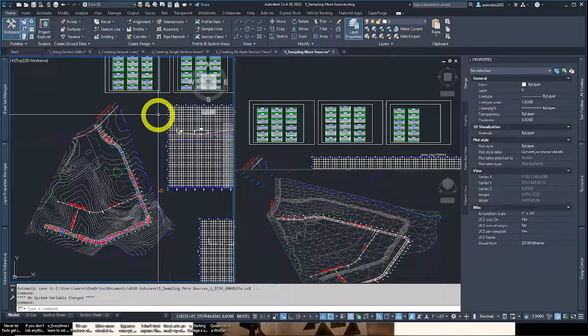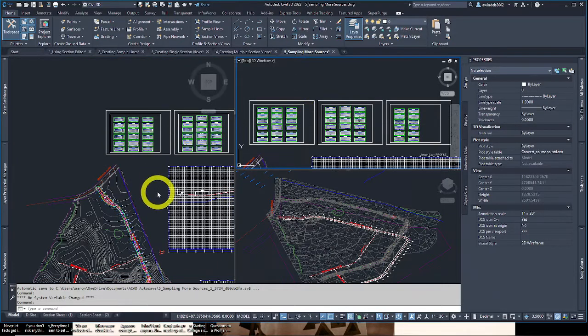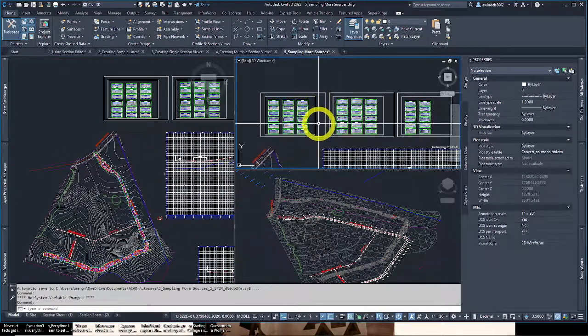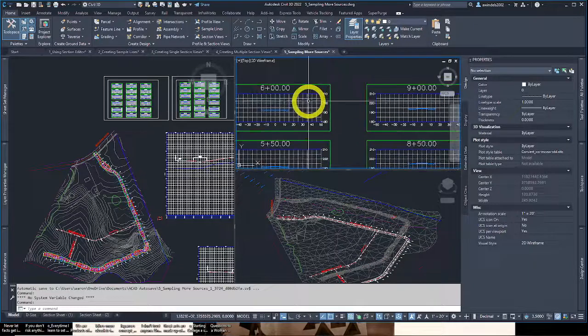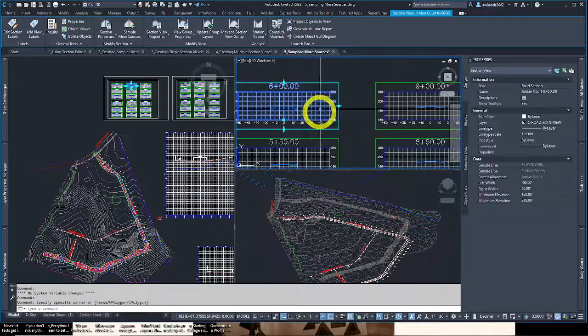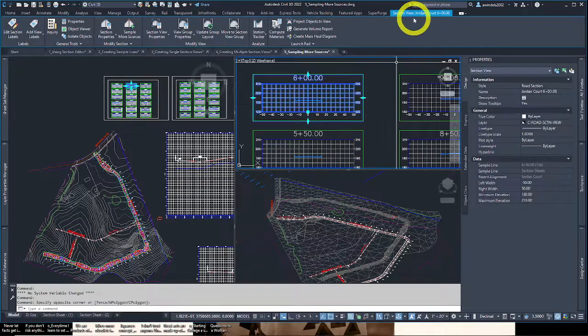So in one of the section views, basically just pick one here in the upper right viewport. It doesn't really matter, you can go in the left or the upper right, but let's just go in the upper right where they're kind of pinned on. You can pick about any one. Let me pick this section view. Make sure you pick the view, so it's picked on the section view. You get your contextual ribbon for this individual section view on Jordan Court 6+00.